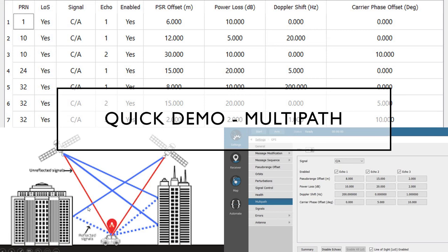If you've got a direct signal and a reflected signal, effectively you've got two signals slightly delayed, so the peak will not be as sharp in its algorithms where it's trying to detect the range, and it will make it harder for the receiver to calculate the exact range.